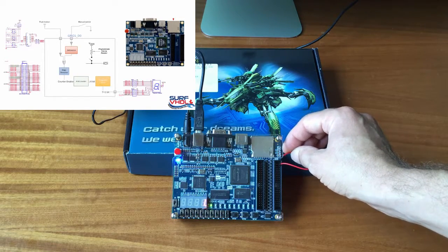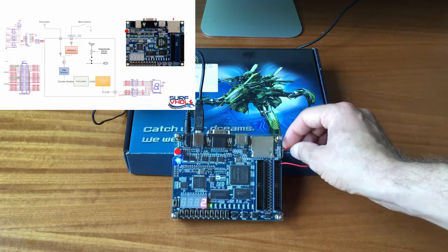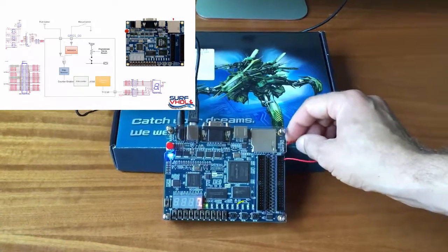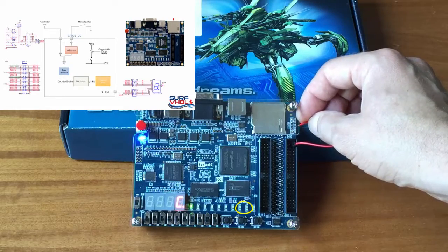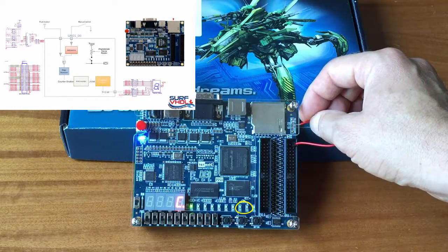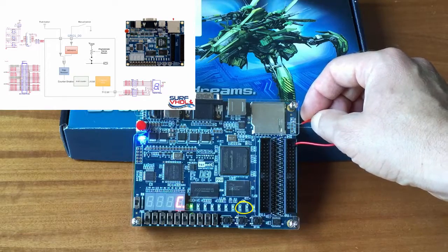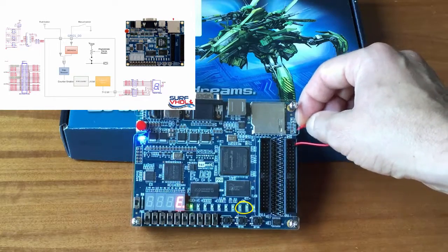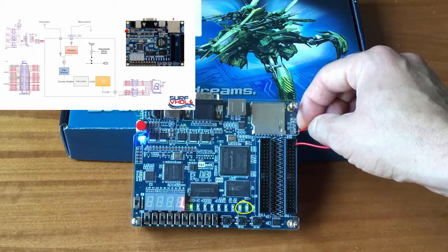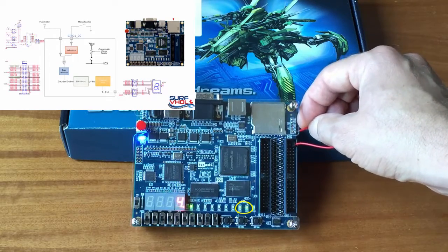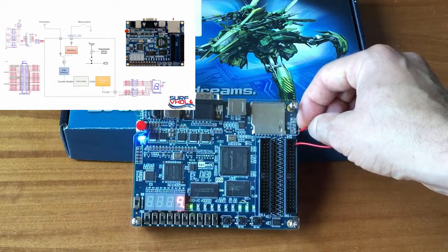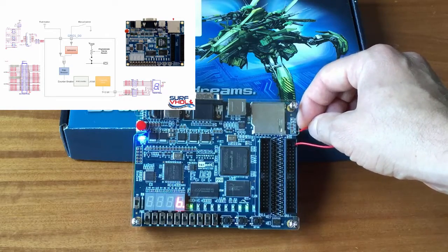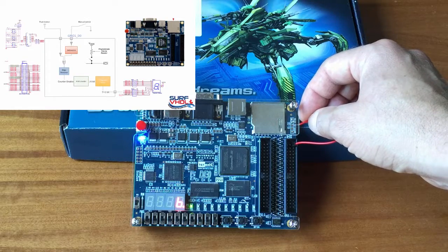As you can see, we have two blinking LEDs: one that blinks fast and blinks with all the input glitches detected, and the second one that blinks once. In fact, the counter counts +1 because we are filtering all the bouncing shorter than 40 milliseconds.